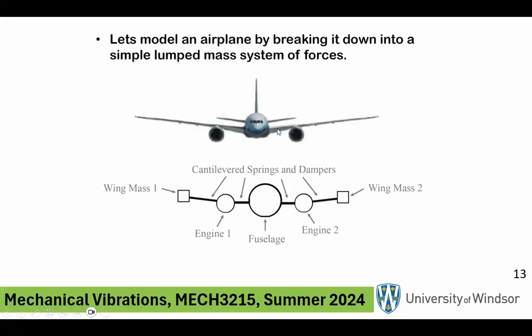Fancy spring, because after all, what is a spring? You apply a load, it's going to deflect. It creates a resisting force for the motion of that mass. The same thing here. I don't have an engine on the right side, but the part of the wing on this side has a mass, so we can think about it as having a mass there. Again, this portion of the wing also acts as a spring. Now I'm going to ignore the damper here because we're not looking at damping yet.